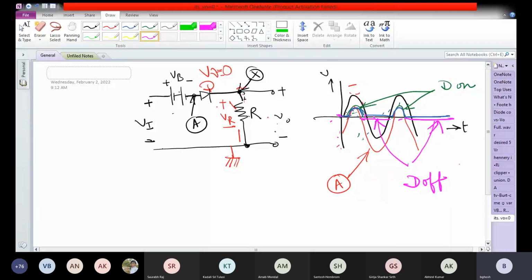Okay, so we don't care whether the diode is in series or parallel or everything. We apply the reasoning. We only care at the outset of the question whether the voltage source is in the shunt arm or in the series arm. These two we only need to see. If the voltage is in the series arm, you just plot the voltage after the battery, and then you forget what is to the left of that point. You concentrate only to the right of the point.